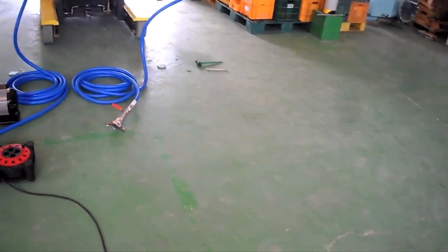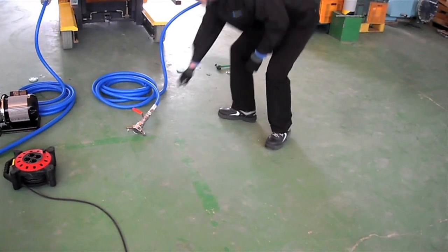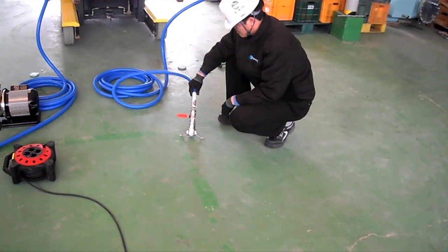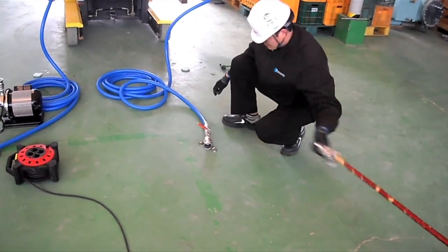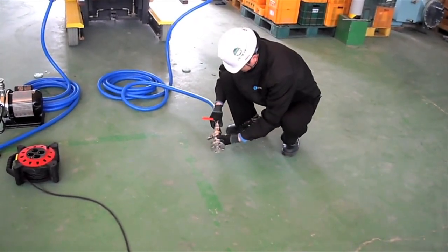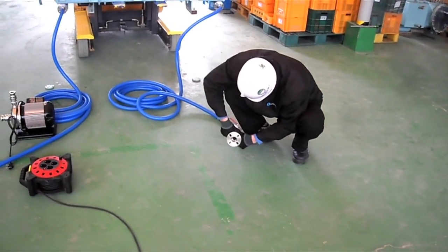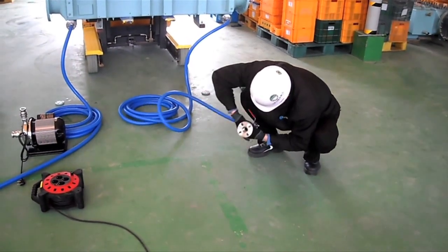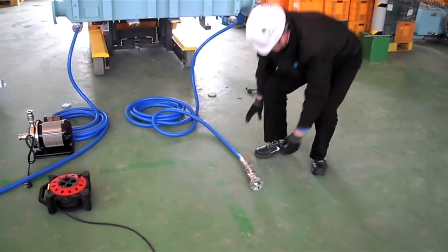5. Drain wastewater containing cleaning agent and open valves V3, V4 to clean inside of ECU. 6. Close valve V3 after flushing out fresh water for approximately 15 minutes. 7. Disassemble pipe AC1 to pipe AC3. 8. Dispose of the collected cleaning agent according to the rules and regulations.